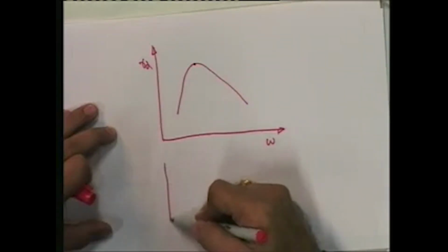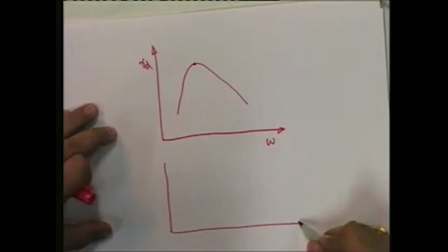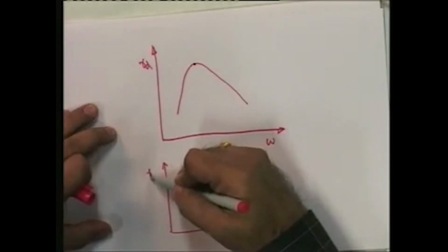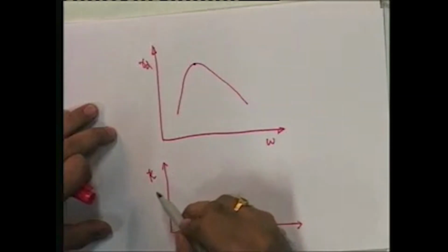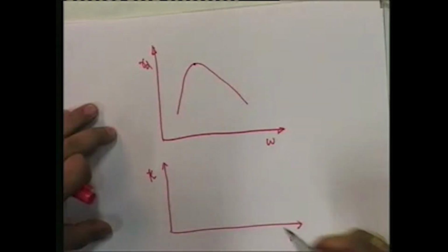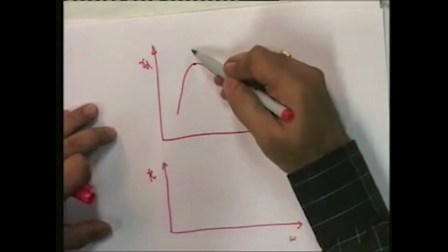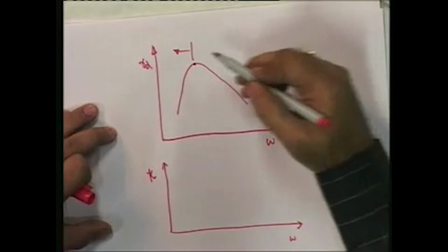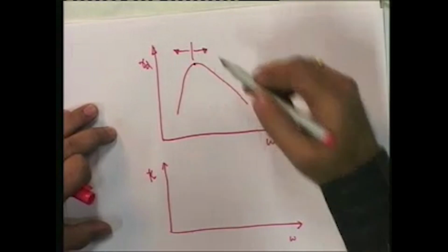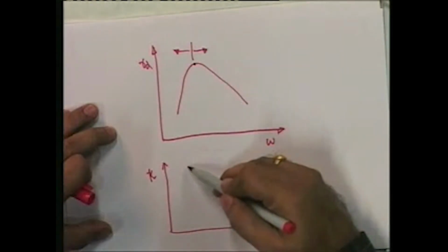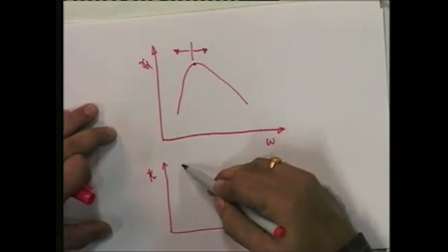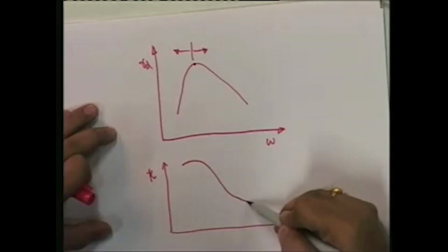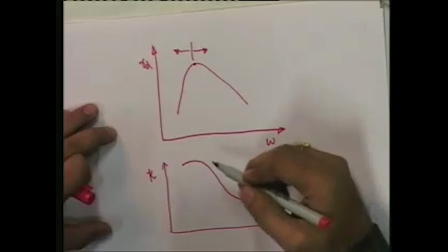If you plot the permeability value K, in meter per second, against water content, this side is the dry side of optimum and this is the wet side of optimum. Here, on the dry side of optimum the soil can have high permeability, and the permeability value decreases for a given typical soil.